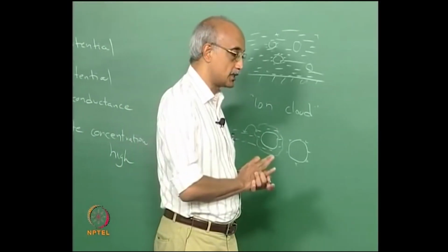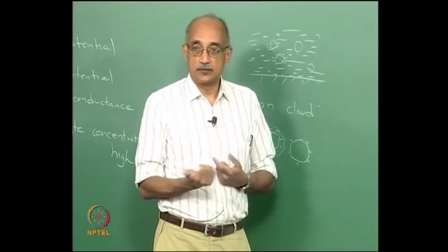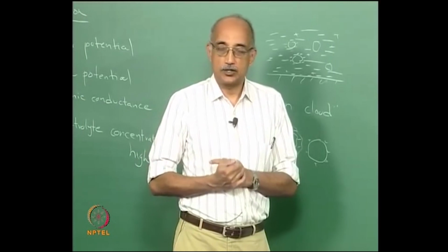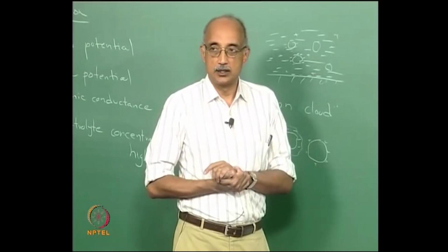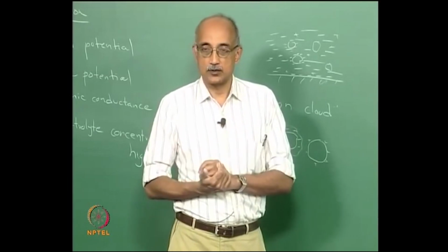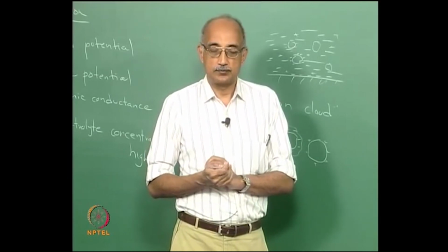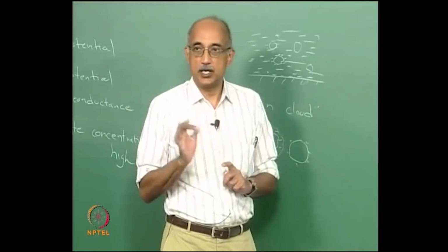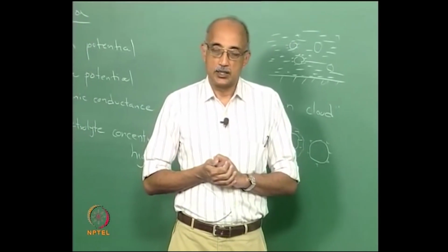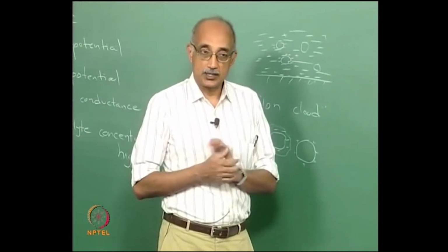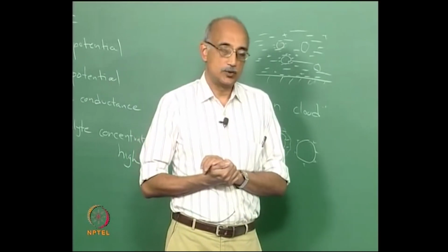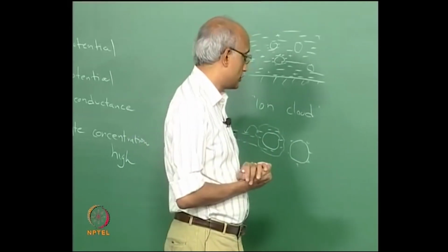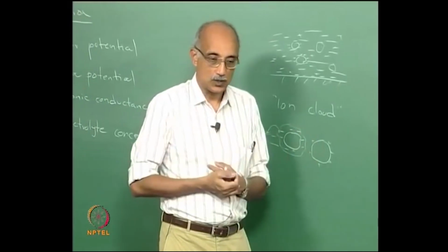It has huge implications for the stability of the suspension. Again, if you can induce charges so that particles in suspension repel each other, they are likely to remain stable in suspensions much longer than if they carry no charge or if they carry an attractive charge. So, by controlling the zeta potential, which can be done for example by controlling the pH of the solution, by controlling the composition of the electrolyte as well as the concentration of the electrolyte, you can influence charge buildup on discrete particles and cause them to either try to come together or move apart.